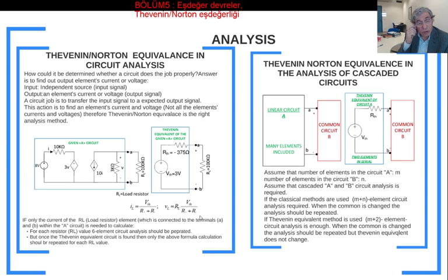But if you don't use the Thevenin equivalent analysis that we did here, for each load, you're going to analyze the circuit once more. So you're going to repeat the analysis for different loads if you're not going to use the Thevenin equivalent circuit analysis. That's why the Thevenin equivalent usage in the analysis is important.